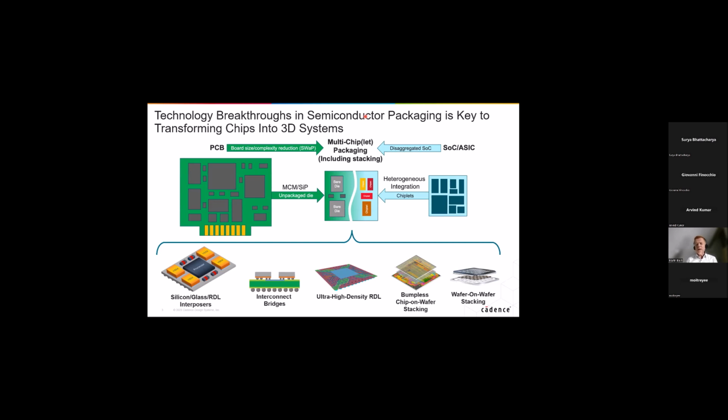So you can imagine from an EDA point of view, there is no super tool that can design all these technologies. Depending on the technology, an IC type tool may be better suited to design a silicon interposer, and other technologies like RDL type interposers may be better suited to work with a PCB type EDA